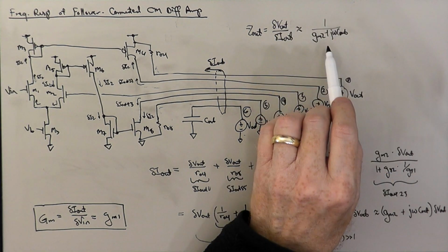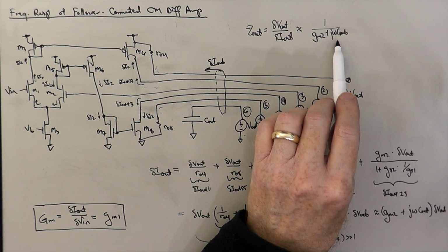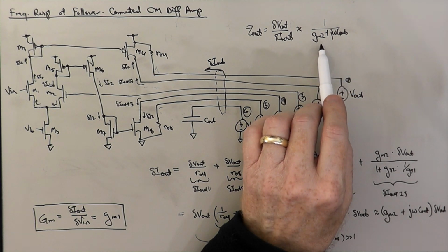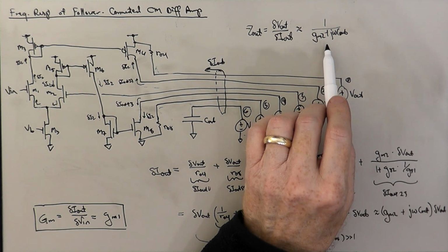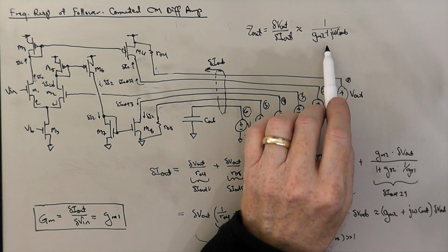When we have something like this where there's a frequency dependent admittance, which is the generalization of conductance, like impedance is the generalization of resistance, it's nice if we factor out the real part here and basically normalize that constant coefficient in the polynomial in j omega to unity.